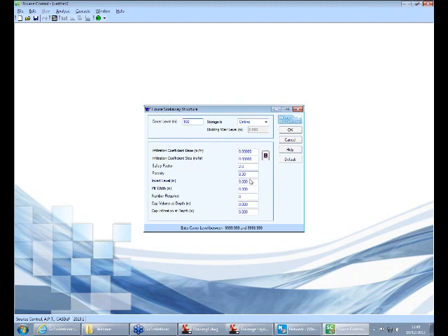So I put in a cover level, I give it an invert level, I make it 1.5 meters deep, I give it a pit width, so it's just going to be 1 meter by 1 meter, we're just going to have one of them. I cap the depth at 1 meter as well, so basically we have storage up to 1 meter, then above that we assume it'll be filled with whatever cover material is going back on top, apart from the manhole itself.